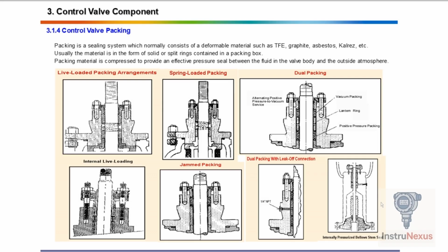This compression creates a tight seal around the moving parts, such as a valve stem, ensuring that the system operates safely and efficiently. However, due to regular use, the packing material can degrade over time, so periodic maintenance is crucial to maintain the integrity of the seal.